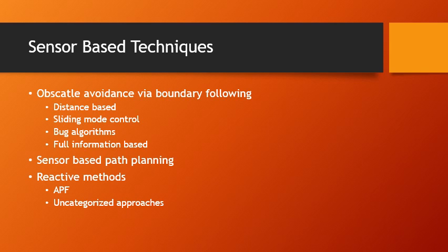Distance-based approaches work based on achieving the minimum distance to the obstacle. This distance is used as an input for guiding non-holonomic vehicles. A common limitation is that the vehicle must have constant speed. By introducing simple heuristics, we can solve this.